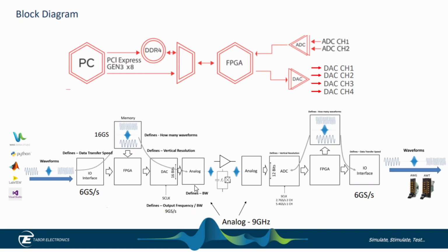That's easy. But for the more advanced users, we could have an LTE data stream. We could have a Wi-Fi data stream coming out, so we can be changing bits on the fly. You could change the characteristics of the waveform on the fly as well for different types of peak to average power ratio or adjacent channel power interference. Or if you're working in electronic warfare or radar, you could be putting different techniques in here to fully test out your receiver, because don't forget we've got 4 channels here, so you can adjust the phase and amplitude and time difference on each one of these channels and create some angle of arrival scenarios.